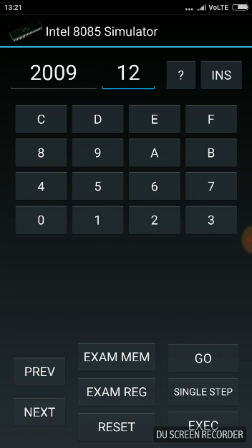So I set up the loop, and first of all, we transfer the contents to the accumulator. The memory location is 2008, and the opcode is 7E. This is MOV A, M, which transfers the contents from the source memory into the accumulator. The HL register pair is already specified when we write MOV A, M.